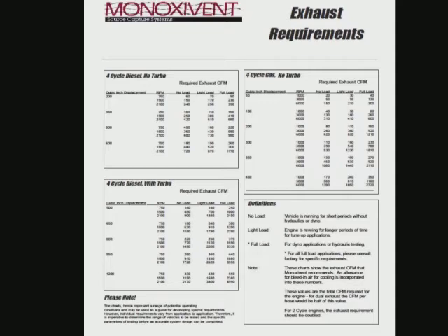So on the bottom right, we've defined no load as vehicle is running for short periods without hydraulic or dyno. Light load, engine is revving for longer periods of time for tune-up type applications. Full load is for dyno applications or hydraulic testing. For those types of applications, you want to work directly with us because there's going to be some extra design criteria that we need to take a look at. So let's just take an example.